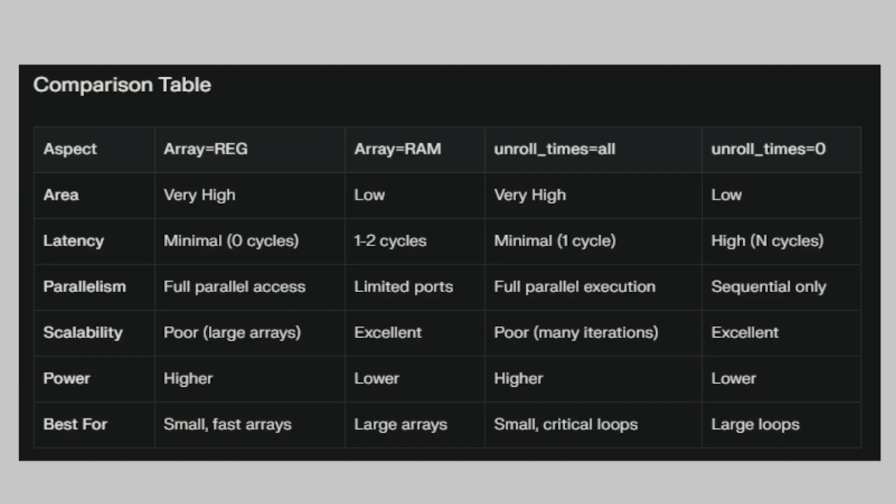So the area consumption will be less, but the latency will be high since the data path to go to the block memories, retrieve it, and get it back to the functional units will be long. Here also the disadvantage will be parallelism. Since there are limited ports dedicated to the block memory, parallelism will be limited. But this has the advantage of giving low power and low area.